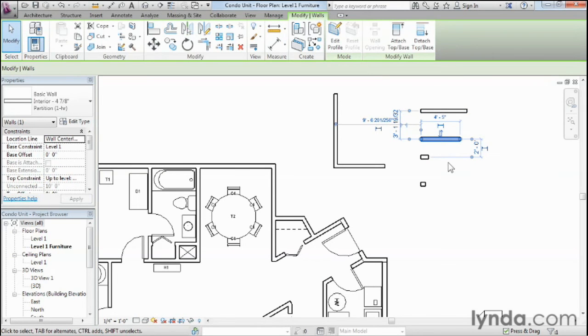Now, that's a really important consideration when we're talking about Revit. This wall is 4 foot 5 inches long. Well, what if I realize that it needs to be a different length? Maybe it needs to be 5 feet. Maybe it needs to be 4 feet. These dimensions that appear on screen are not just information. This is actually how we interact with the object after we've created it.